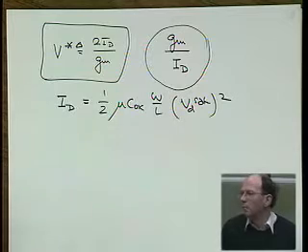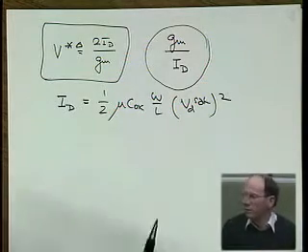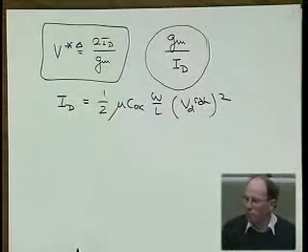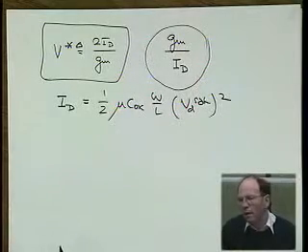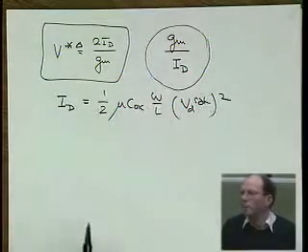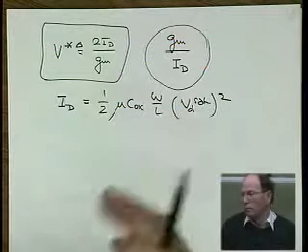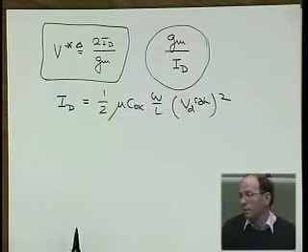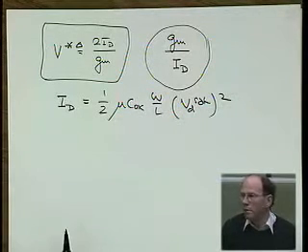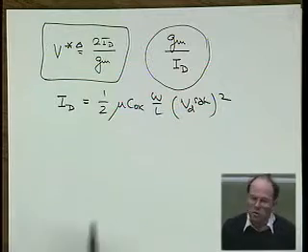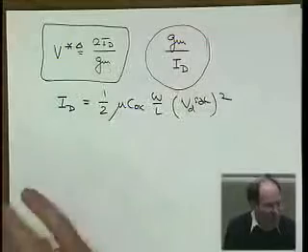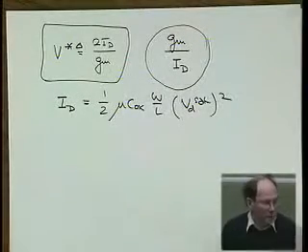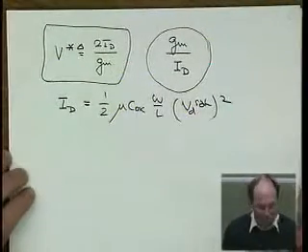And the errors are going to be because SPICE uses 64-bit floating point numbers and you use 2 digits, right? Or more typically, you miss or do not accurately model a parasitic in your circuit, especially a capacitance that SPICE will. And so then you get some discrepancies there still. But this stuff here, it's going to be dead on, because we define it that way, right?